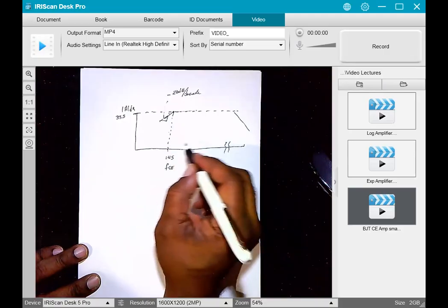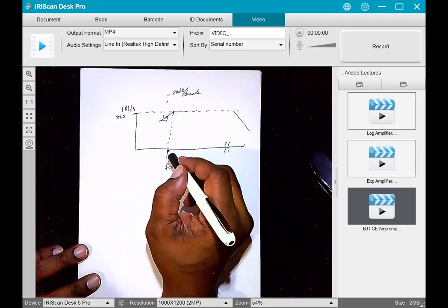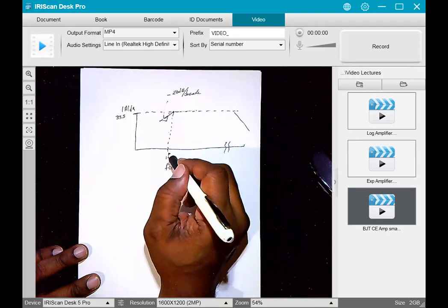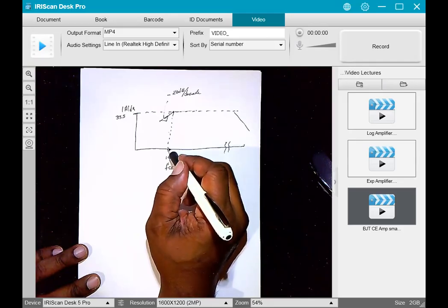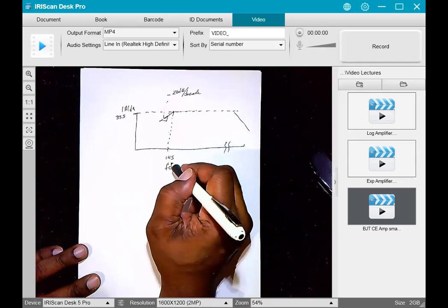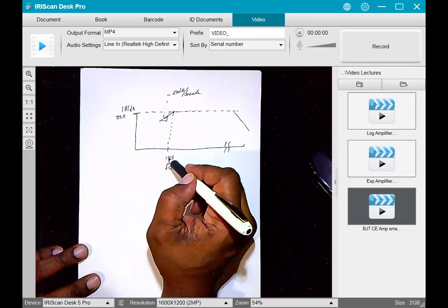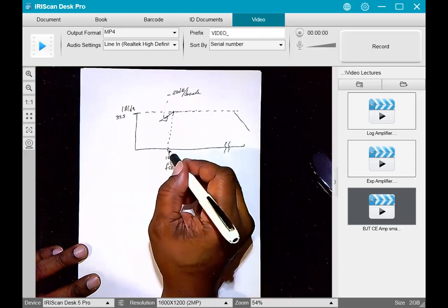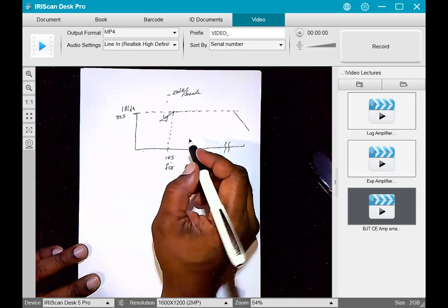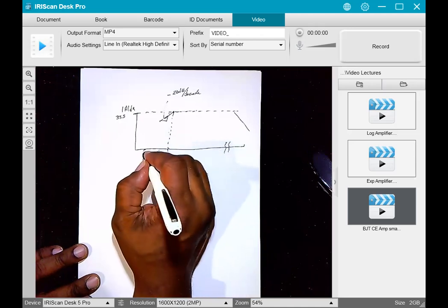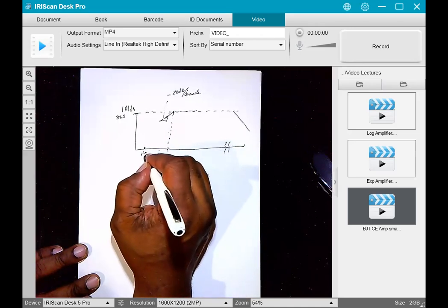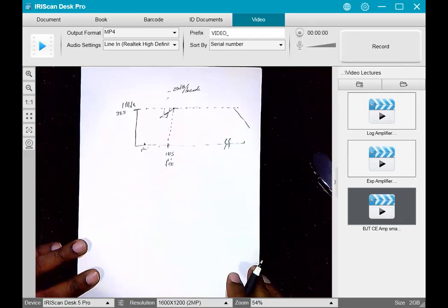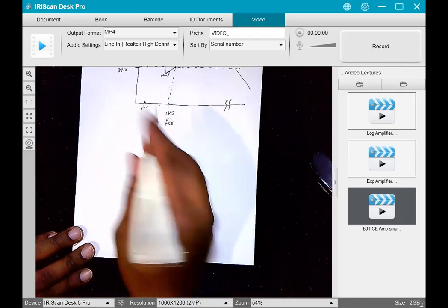and this is 145 hertz, 1 decade below that is basically this divided by 10, which would be what? 145 divided by 10. Frequency would be 14.5. So over here somewhere at 14.5, well, no, let me do it down here so I don't mess this one up.